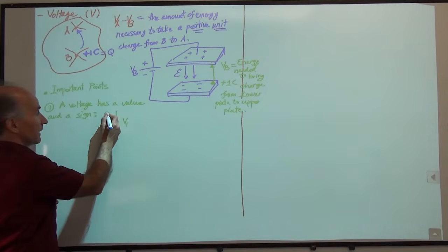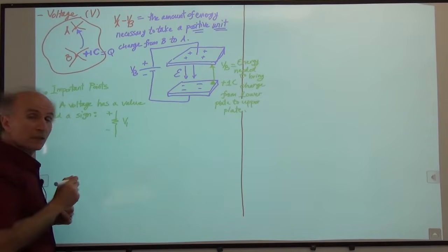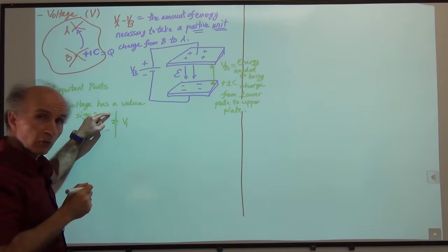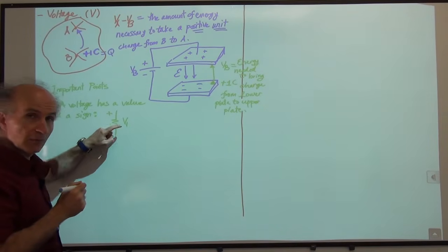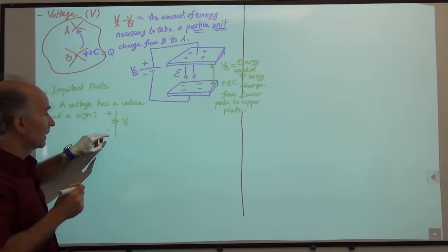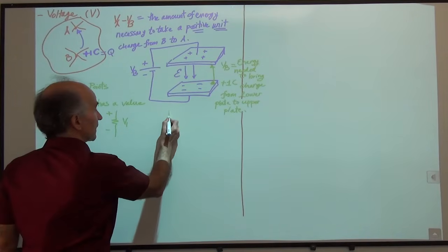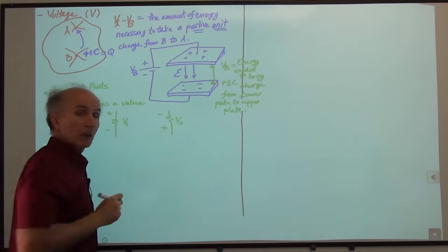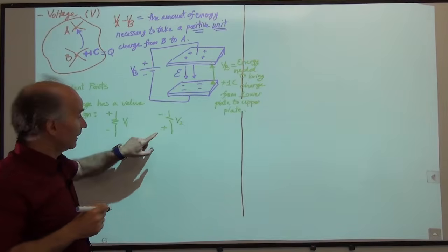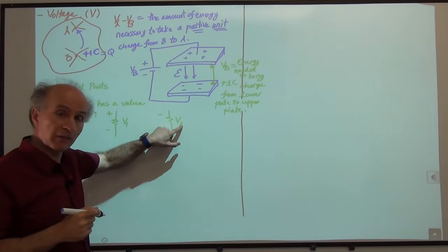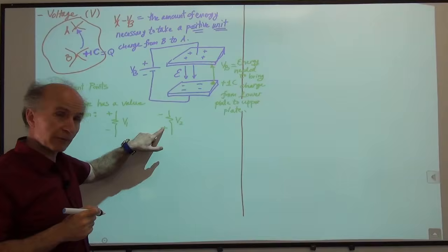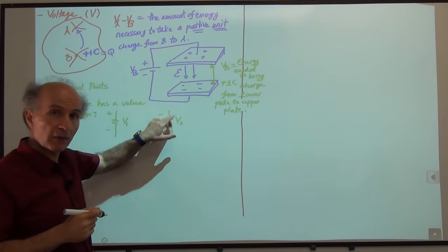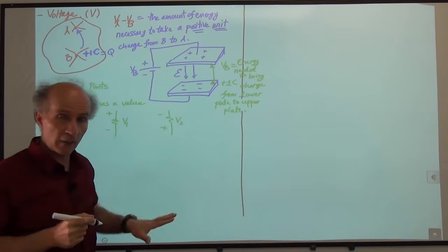For example, we say the voltage is positive here, negative here, meaning that this point is, for example, 1 volt higher than this point, V1 volts higher than this point. Or I can have something like this, in which case this means that this side is higher than this side by V2 volts. So we always have to have these 2 notations plus this value for any voltage that we specify anywhere in our circuits.